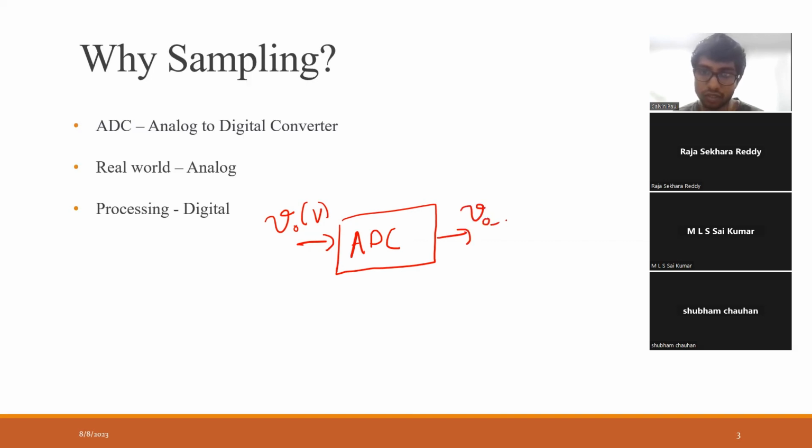Let us say we output D, which stands for digital, and it would be a number which represents this voltage. Suppose the voltage here was 1 volt, then let us assume this number will be 1000, in the decimal domain. Or if it is 2 volt, this would show 2000, etc. So this is how this voltage signal is converted into a digital value.